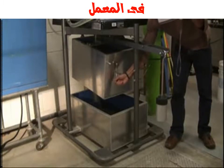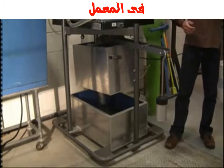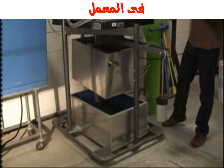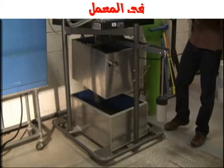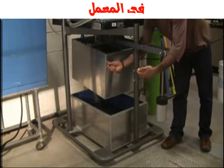Similarly, when the lever is turned clockwise in the horizontal position shown, the drain at the bottom of the tank will be unplugged. This is an actual demonstration on how to measure discharge. Now turn the lever counterclockwise in the vertical position and start the timer.